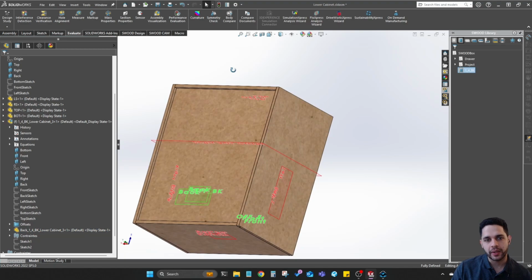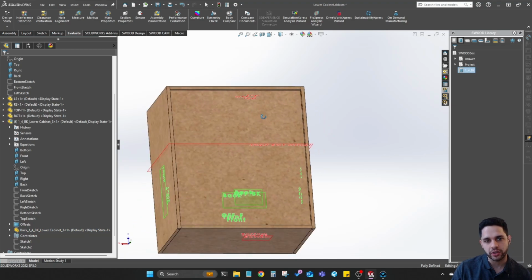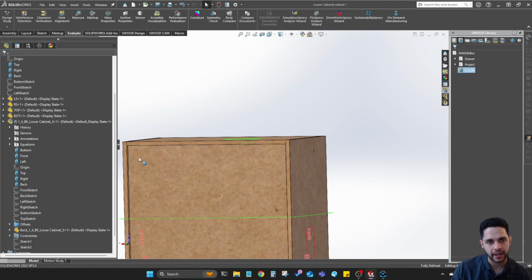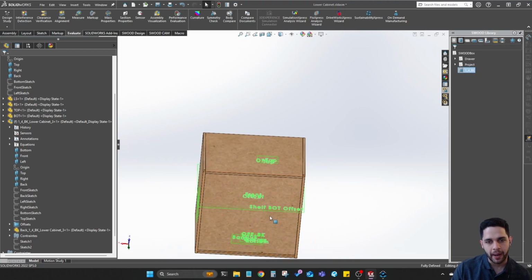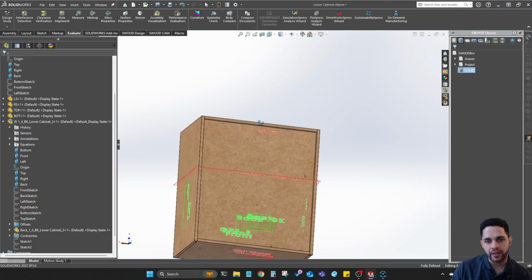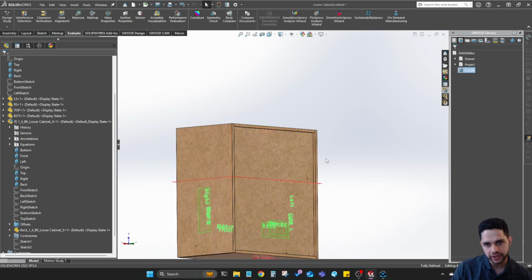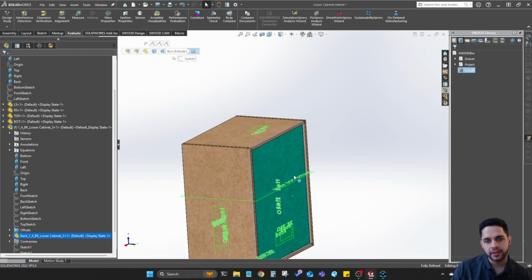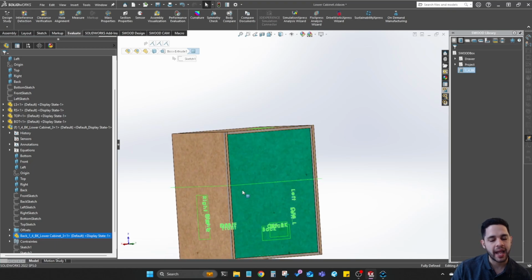So we need to install stretchers, which are going to be pocket screwed into the side of this left side panel, right side panel, bottom, top, and then in between where the stretcher interacts with this back, we'll apply some hot glue to keep that panel rigid.